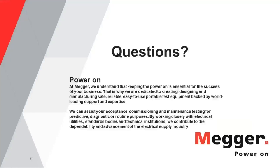Okay, so when testing cables, what you need to consider is that cables represent a very high capacitance, so they can store a lot of energy, and you might not be able to charge that capacitance to determine if your insulation is good or bad.